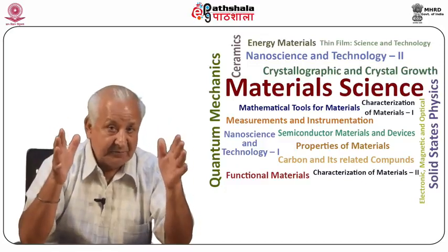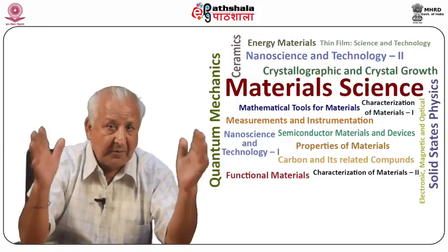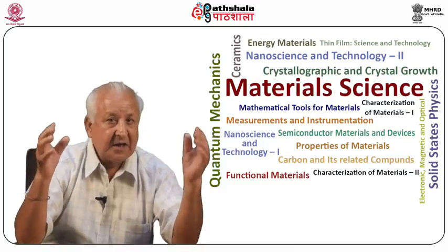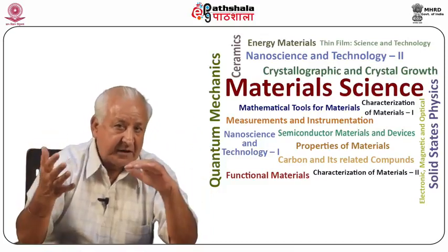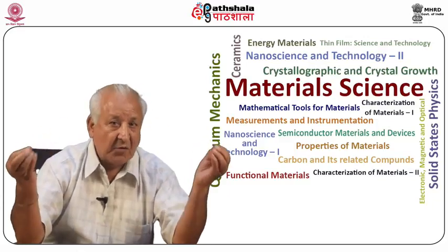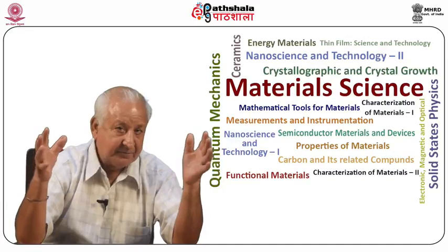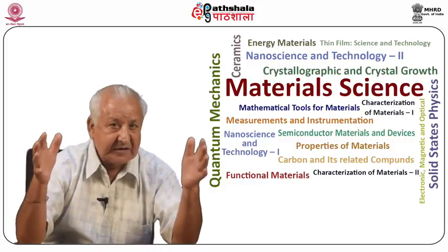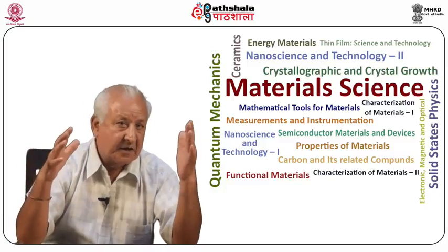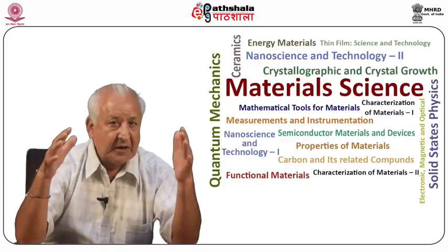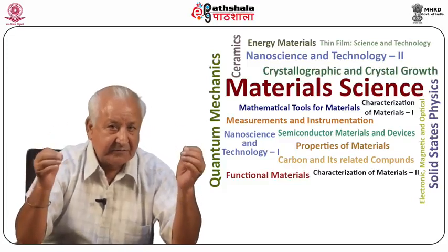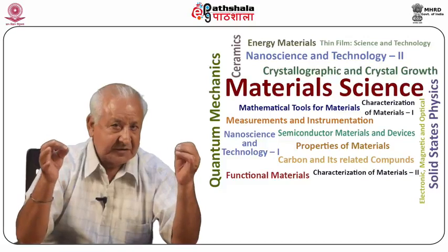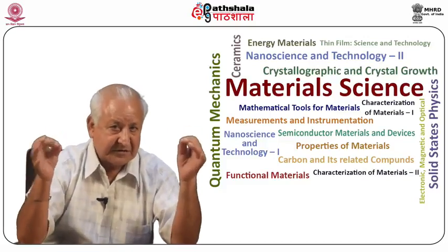At the equilibrium state, the material is completely molten above the melting point and completely solid below the melting point. As such, the transition of the material from its molten state to solid state is quite fast at this equilibrium state. The problem for the crystal grower is therefore to control this rate of transition from molten state to solid state in order to ensure that single crystals grow. To achieve this, a small volume of the melt is permitted at a time to pass through this transition temperature in order to achieve crystallization.